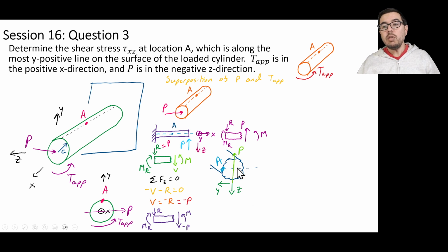That shear force, that internal shear force P, that was what V was, I can draw it upward as we see here, because V would have been downward, but that would be minus P. So now I put a positive P and I can draw upward. And again, that lines up very nicely with what we have here on this diagram.